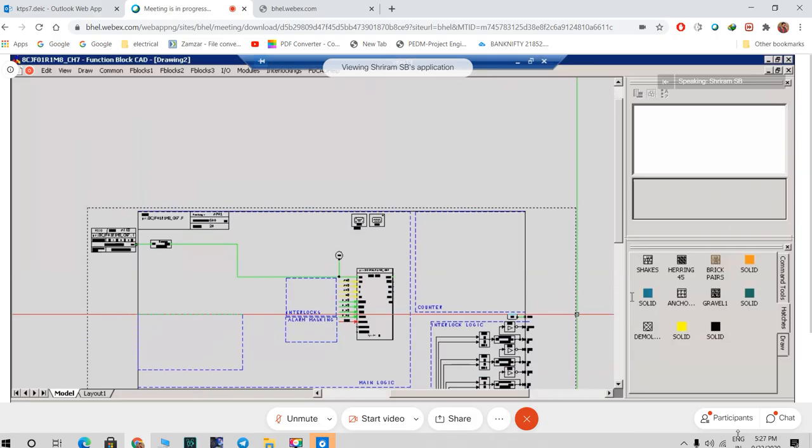Or with the existing thing, if you want to use, the only possibility is that you have to merge two interlocks by using AND or OR gates, whatever is your requirement. And text also you can merge. Suppose you want to use pressure is less than this, and then drive is on. So both you can make an external AND gate and then connect it to your child loop.